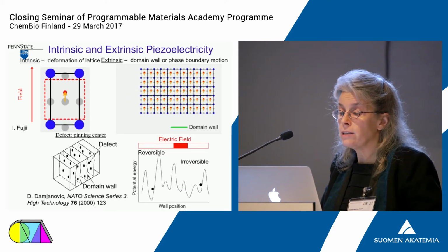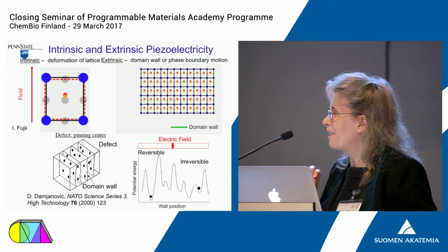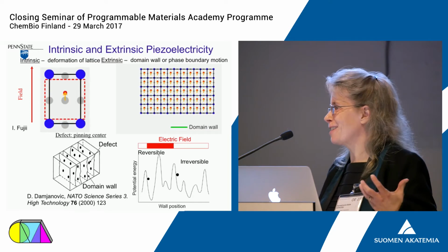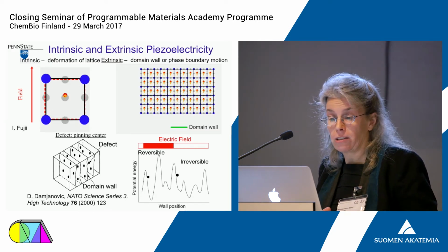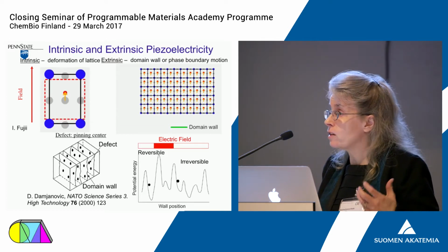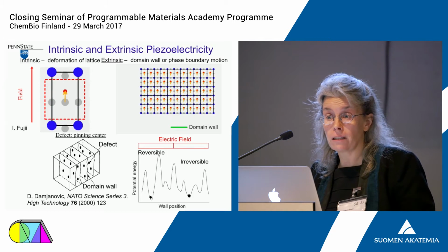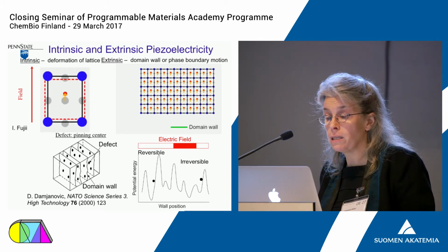Although I showed in the schematic the domain wall moving in a very uniform fashion, in reality this is a planar defect. It is moving through a solid which is in itself defective, and the net result is that I have to move these planar defects past the defects in solids which act to pin them.